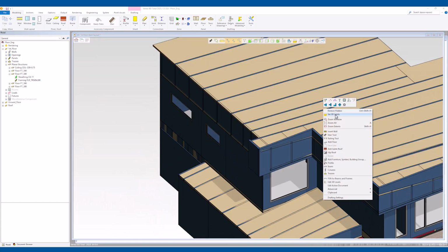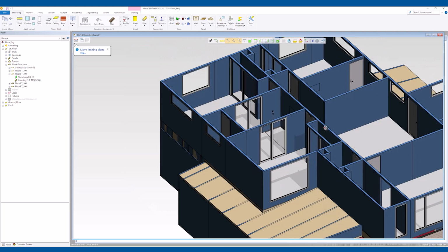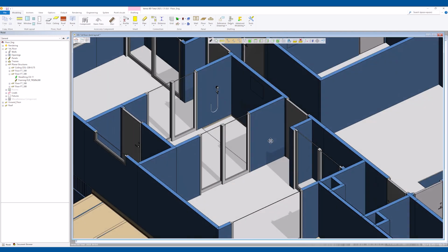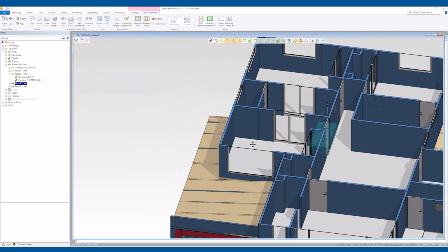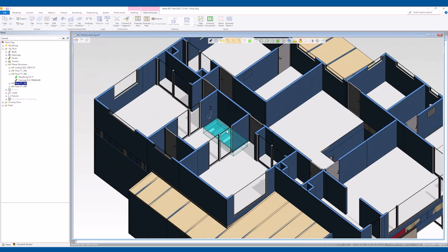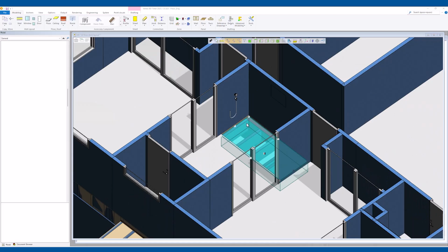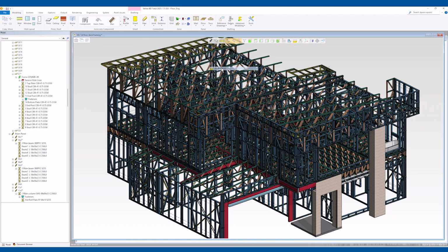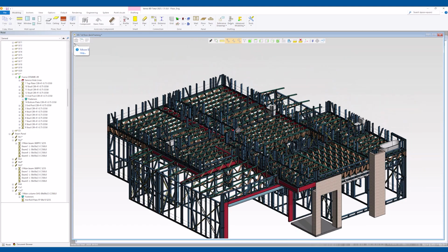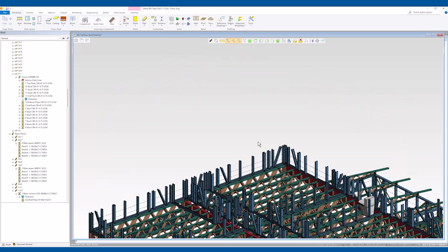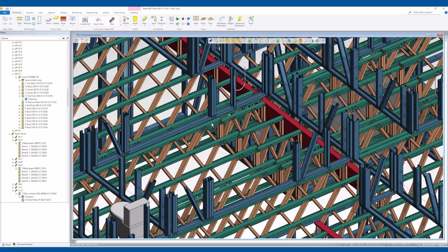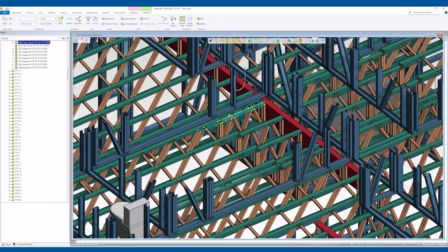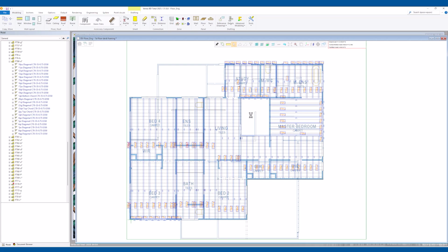And these step downs have already been detailed in both the architectural model and framing models. So usually the engineer will require a bit of extra live load or dead load in these spots. So that's what we're going to add first.